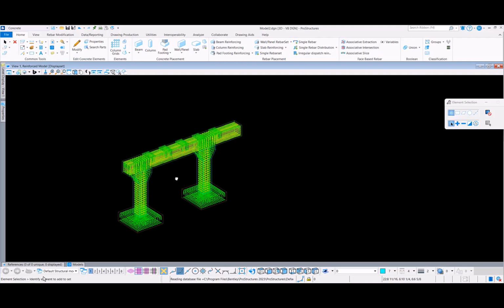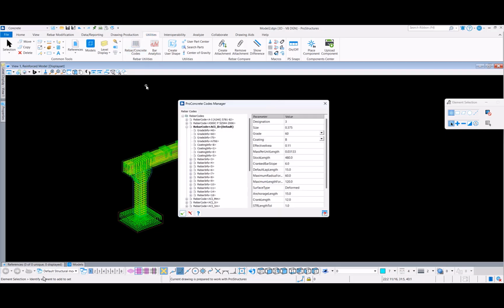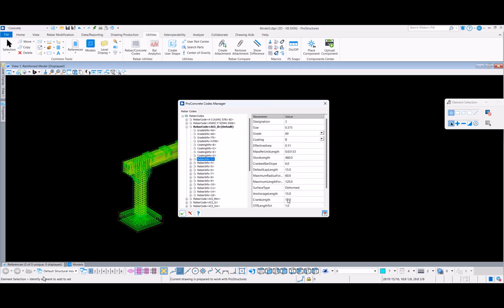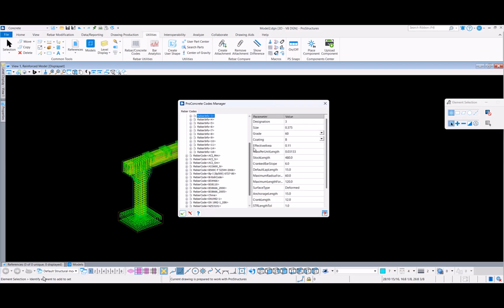The tools available in the software are just designed to do all that kind of information and generate concrete quantities, generate rebar quantities. Well, and using this, even different detailing codes. Of course, the ACI is there, but if we're doing projects international, we can just use all other codes as well, British, Australian, so on and so forth, that are part of the solution. So we can use all of them and the way they call their bars, the way they are bending the bars, and the different nomenclature that is used to call the different elements of a bar detail.